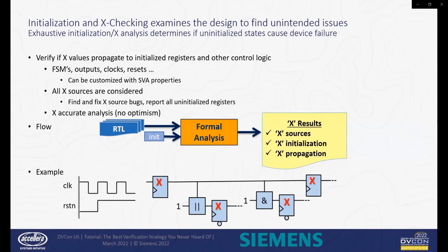At initial power up, all registers in the design would be in an unknown state. As the reset is applied, the registers with a reset are initialized while the other ones are not. As the init sequence completes, an analysis is done, reporting all registers which are uninitialized. This is investigated to ensure a correct initialization sequence.